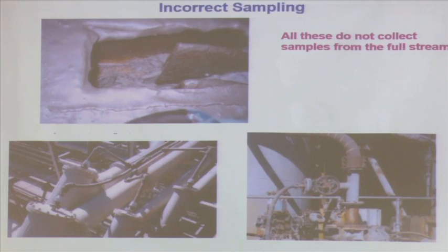But what will happen? If my pollutants are being transported across this, at different depths you have different pollutants, because, as I said, at different layers you have different velocities, and across the width at different locations I may have different things. So if I am taking only a small portion, not cutting the entire stream, I am introducing a bias. I may miss some of the particles which are bypassing it, so you cannot cut it short; you have to have some method of cutting the entire stream across.